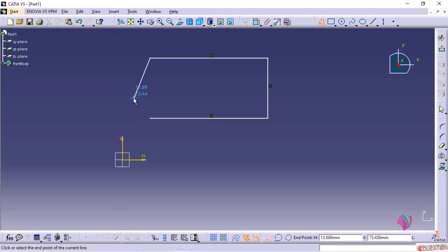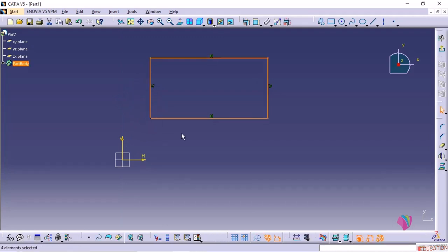You need not create here. You can directly move over and join. So all the exercise that we have done at the start can be nullified by using this tool. So you can use this method to create horizontal and vertical lines very easily. Now let us give the dimensions. Here this is the dimensional constraint. Click on this. Click here. You can see.